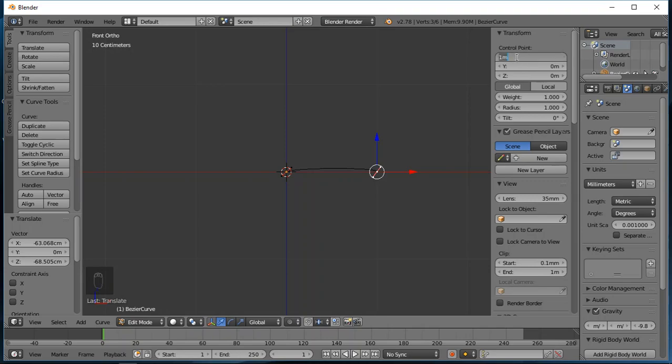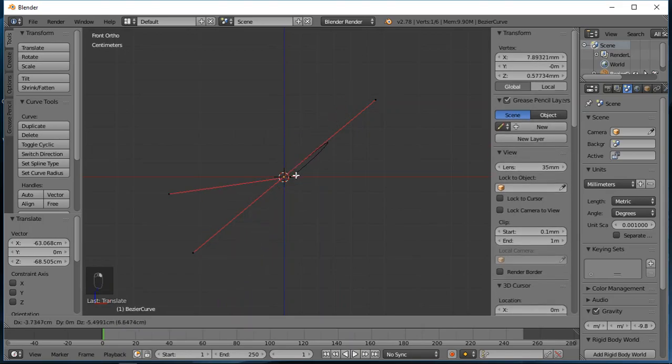Now this is gonna be at 4 millimeters, 0 in the Y and 0 in the Z. Now I can zoom in to that 4 millimeter gap. Now I don't want to go too far before I move the control handles to a good amount. Again, make them smaller so I can see.